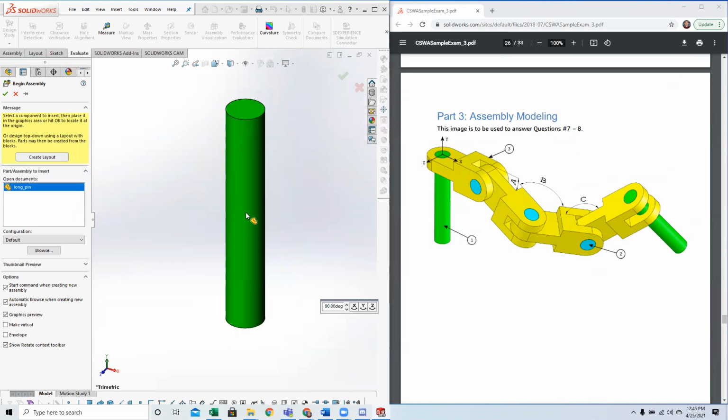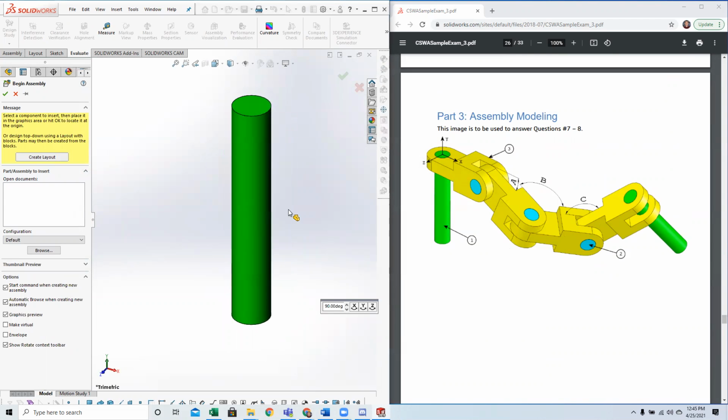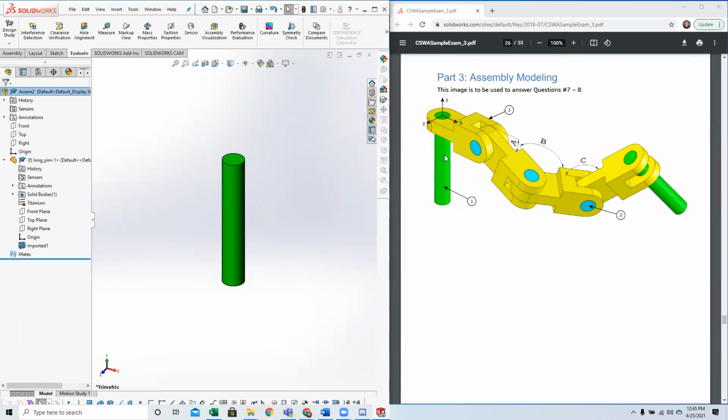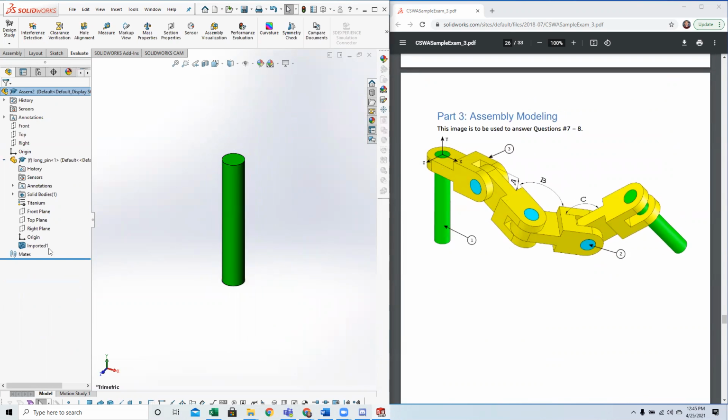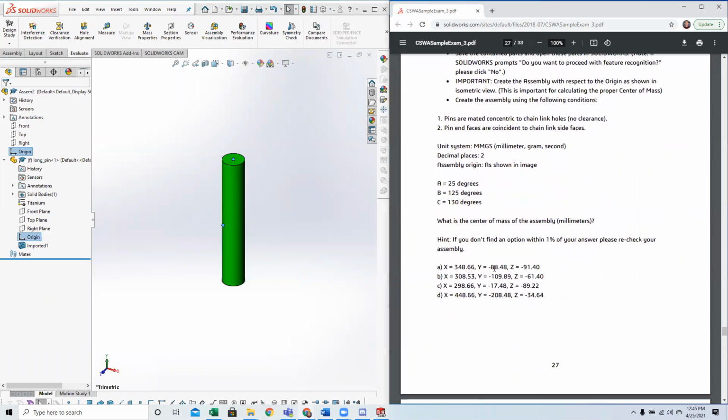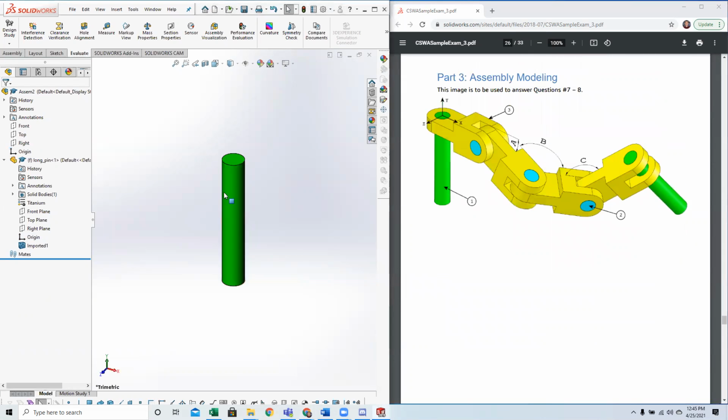And by doing this, if I insert right here, we just have to check now if our origin of the entire assembly is aligned with the origin of this part right here. And it looks like those 2 points are at different positions. So I'm actually going to want to align those properly before continuing. I think there's 2 ways to do this.